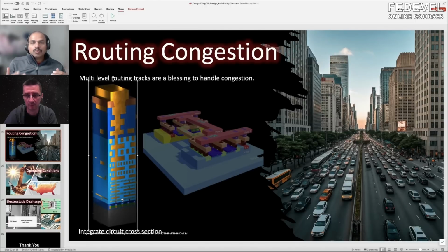So for that reason, we want to stay with orthogonal structures. So if you make routing like this on one of these layers, then it can break where the corner is? Yes, exactly. You take 45 degrees, that may not be strong enough. I didn't know this.